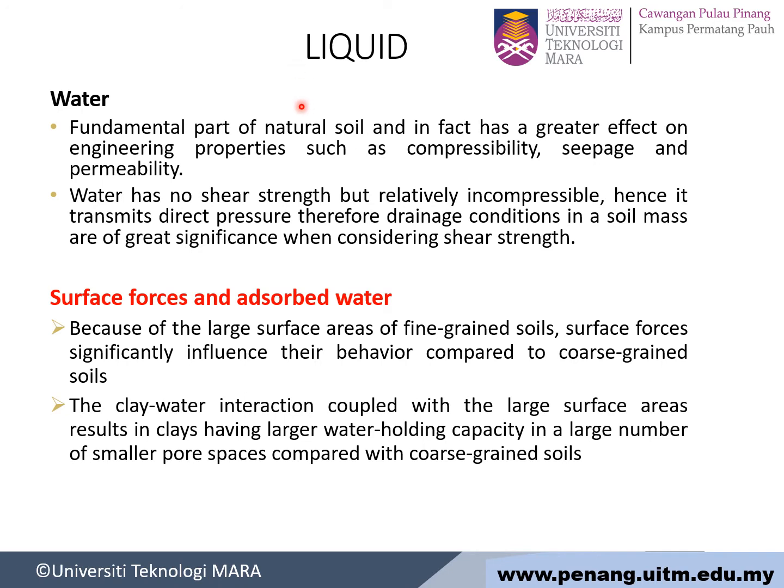Okay, now continue to liquid, for example water. Water is a part of natural soil. It has a great effect on engineering properties, so it is related to compressibility, seepage, and permeability. For your information, water has no strength but is relatively incompressible, meaning that we cannot compress it. Hence, it transmits direct pressure. Therefore, drainage conditions in a soil mass are of great significance when considering shear strength.